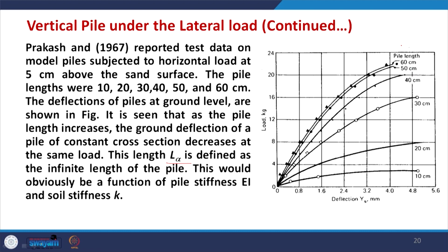Now, if I see, there is a gap between 10, 20, 30, 40, but the 50 and 60 curves are very close. That means, for a given load, for example, if I assume a load of 8 kilogram force and draw a line, you could see that the deflection decreases very much when I go from 20 to 30, but then the rate of decrease becomes very small, and at the end there is hardly any difference.